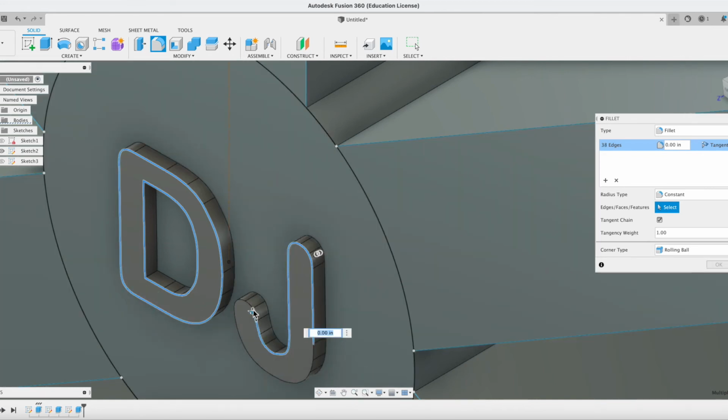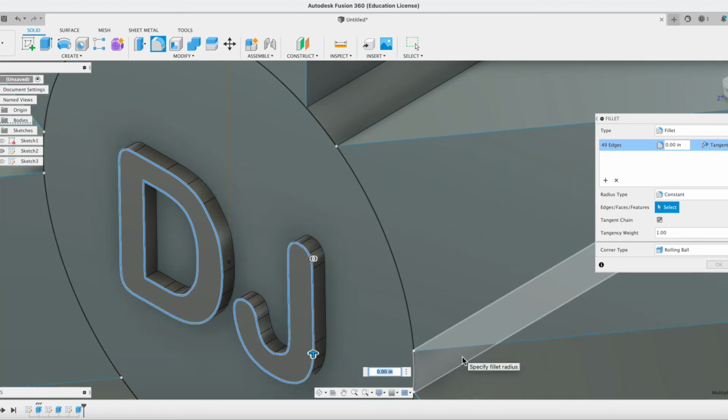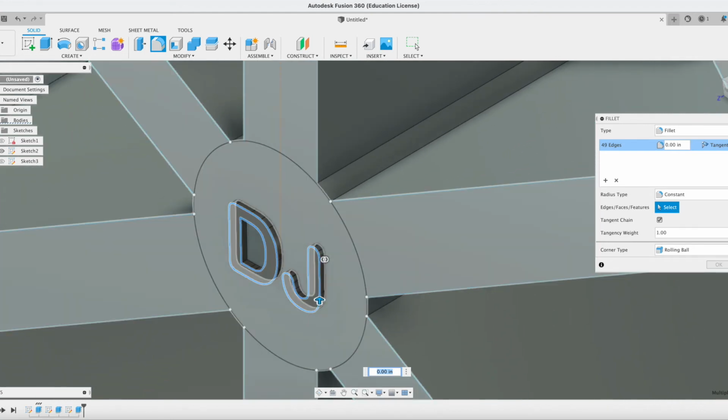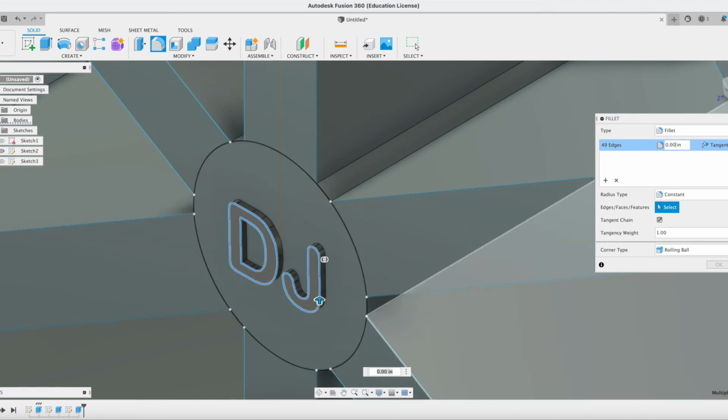These are a lot. Okay, usually there's this thing called rule fillet, which will fillet everything at once. Sometimes it doesn't work. I don't know if that's a bug in the software. It depends on the type of object. Sometimes the type of object is the same and the rule fillet doesn't work. So not my favorite feature. And usually when you do it, it slows down your computer and Fusion 360 a lot, and it takes forever to load. So not my favorite, but less work.